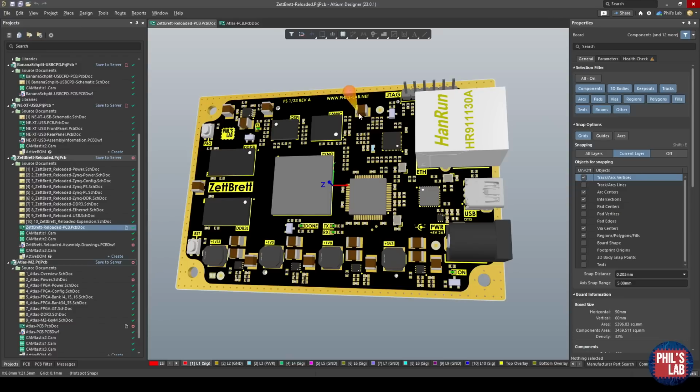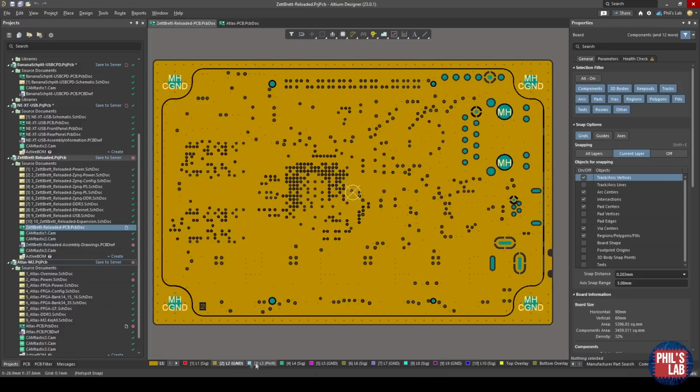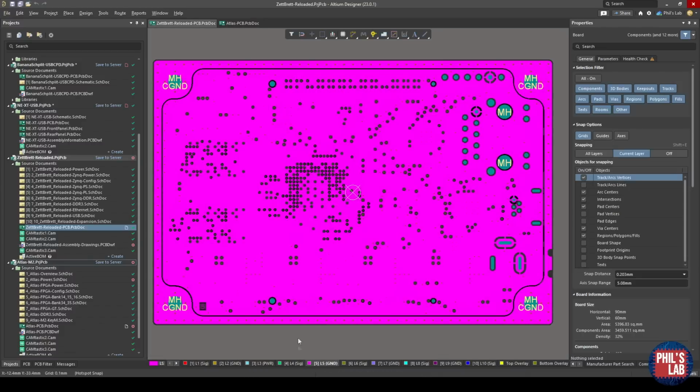For both of these designs, of course, I had to generate manufacturing data, and for any design you want to manufacture, you have to generate this data. Before you get to this data manufacturing step, however, you really need to make sure your design is checked thoroughly. This is starting by going through the schematics, looking at the PCB design, or the routing, making sure you've designed the stack-up properly, you have no splits, and so forth.